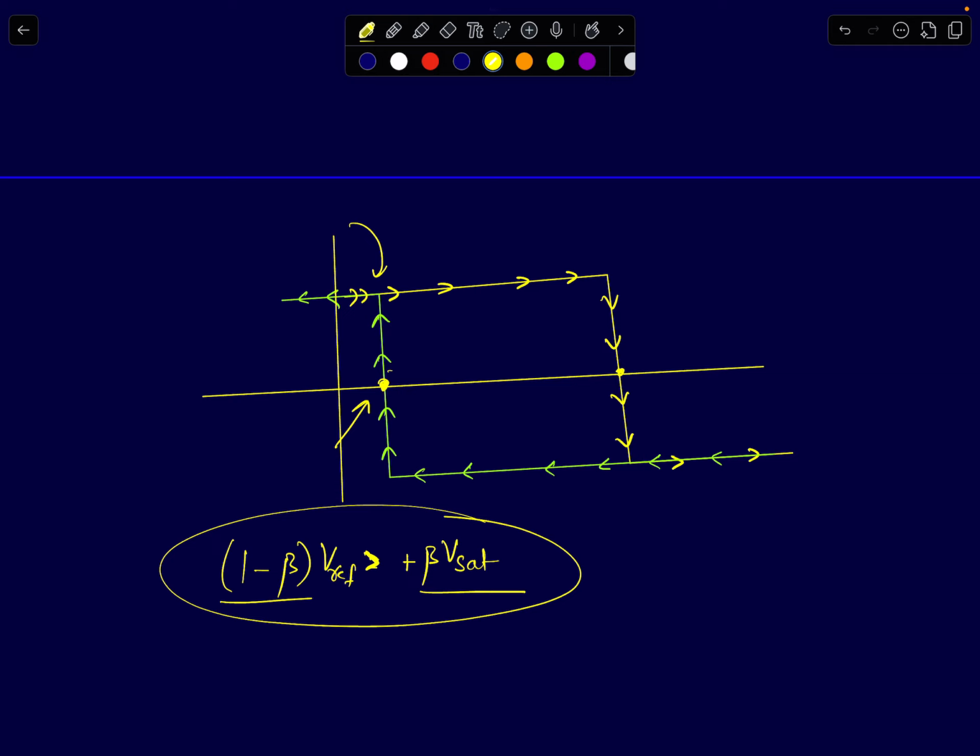You'll later see, when we talk about single supply systems, how all of this will be very useful in building Schmitt triggers for single supply systems. So this is another way: by adding a fixed offset, you can realize asymmetric threshold voltages which are not symmetric around the zero point on the transfer characteristics.